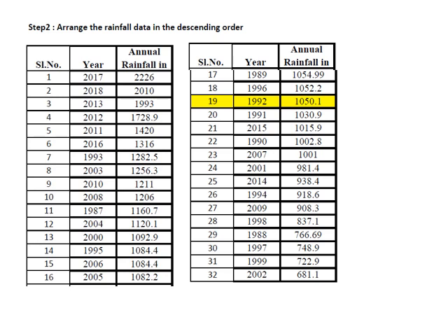It is not that whatever survey you do on the site, to whatever level you do the survey, suppose you do the survey to 128 level, that's why you fix the bund to 128. It is not like that. It is the amount of rainfall occurring in that particular catchment and how much of it is converted into runoff that is to be decided, and then the storage volume has to be decided.